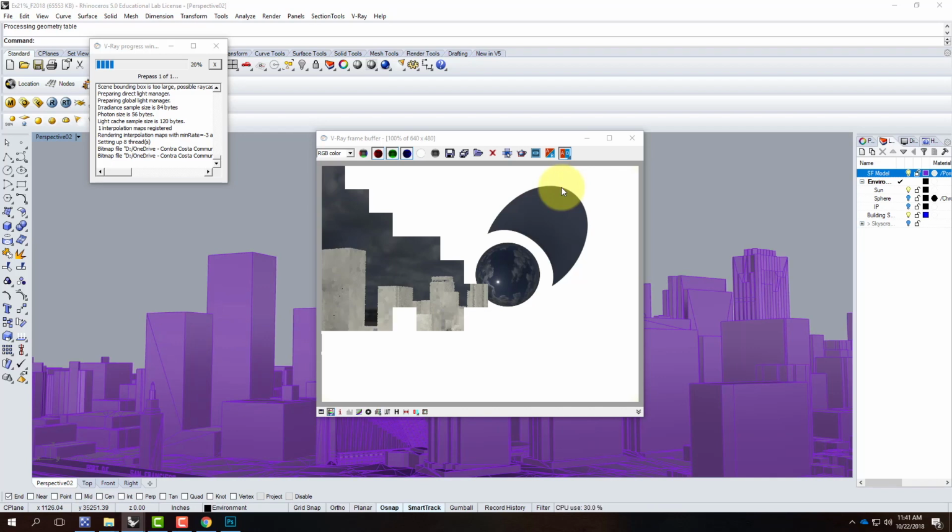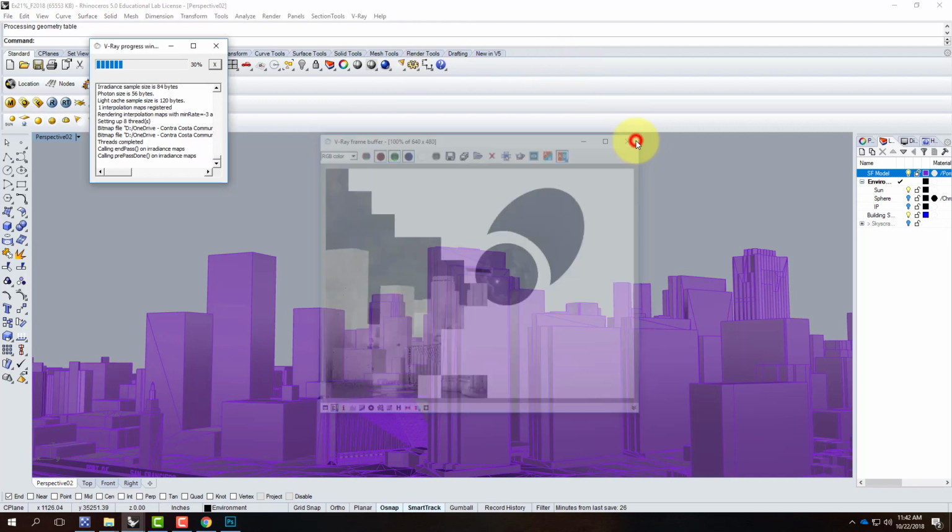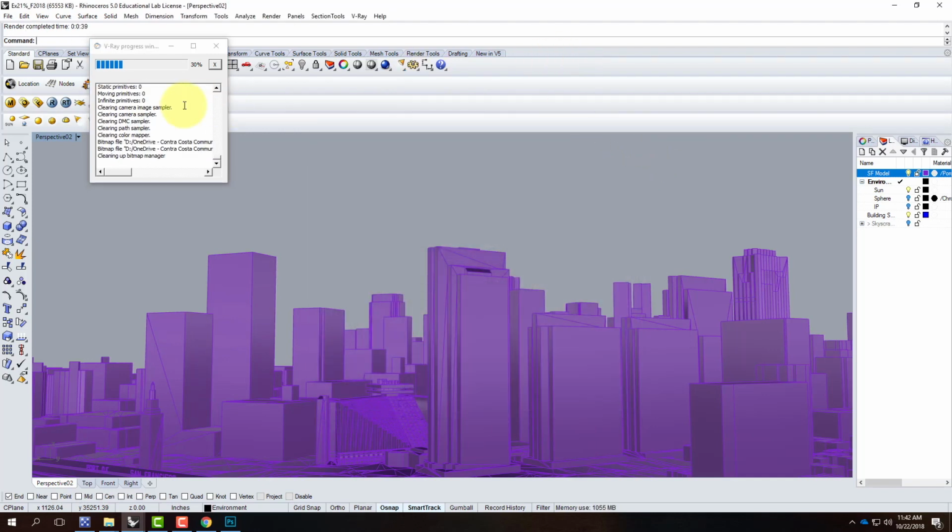Now, right now, the sky background, unless it's a really stormy day, is looking far too dark for the overall rendering. And you can even see that already in the preview. So I need to be able to modify that color. I need to be able to lighten the HDRI. And this is where HDRIs are so valuable. Remember, just like a high dynamic range image, when you capture it, you're taking multiple exposures. So I can shift how light the overall image is based on V-Ray settings.